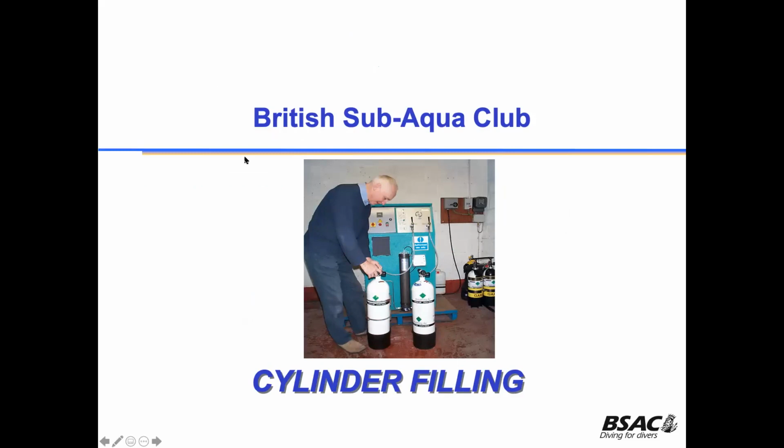I believe they're either every 6 months for a commercial compressor or every 3 months, something like that. But there is a time requirement when you must start to have your air test, and you've got to keep that record. But you also keep a record of all your fills and how long the compressor's been running, right? And some of these compressors have quite sophisticated instrumentation on them.